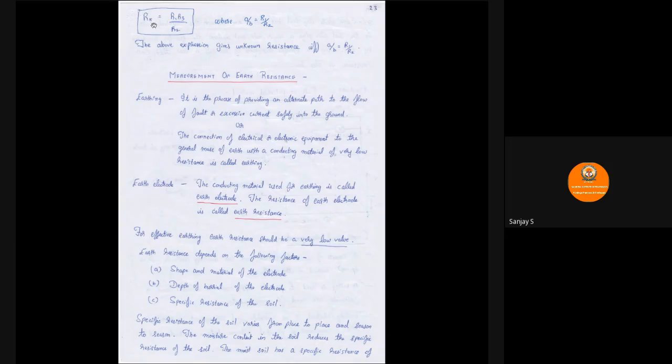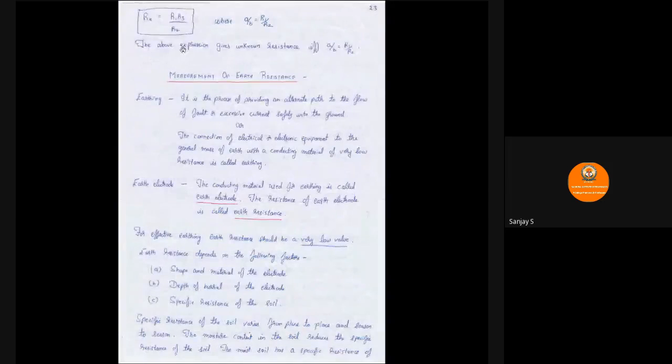So from this you can understand that again we have the same thing, product of opposite resistances are equal. You can just observe the circuit, R1 R3 is equal to R2 into Rx. So R1 R3 is equal to R2 into Rx will give us the bridge balance condition. So this finishes with Kelvin's double bridge. So Kelvin's double bridge for measuring the low resistance value.